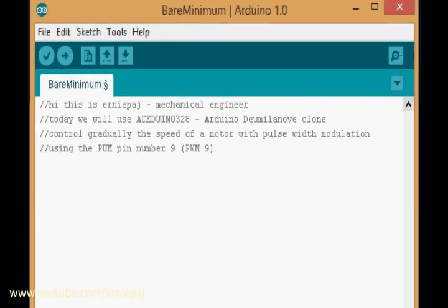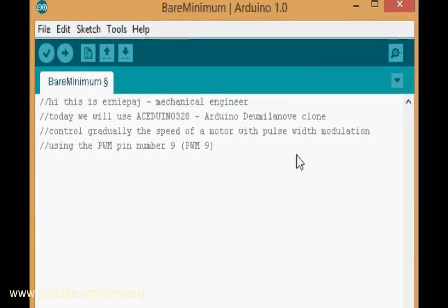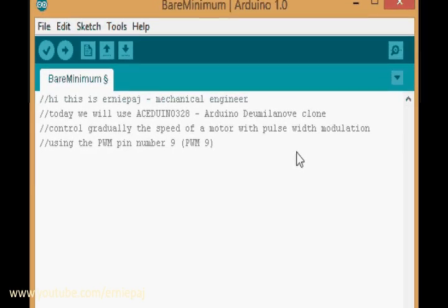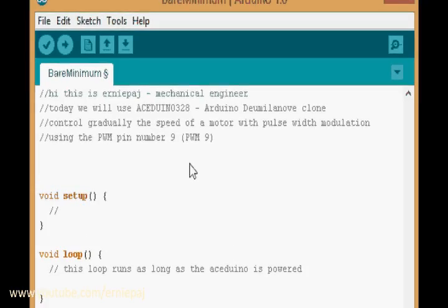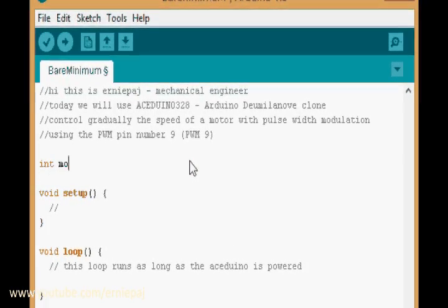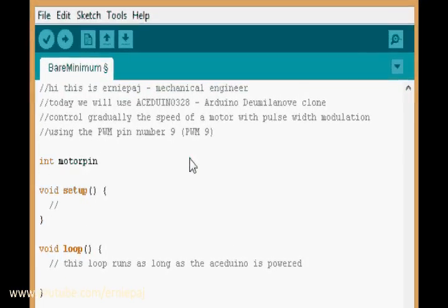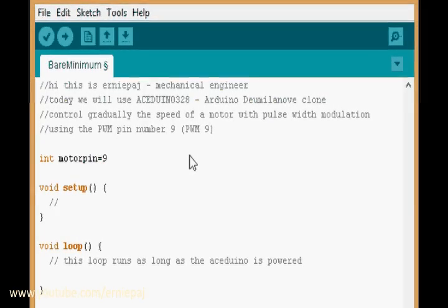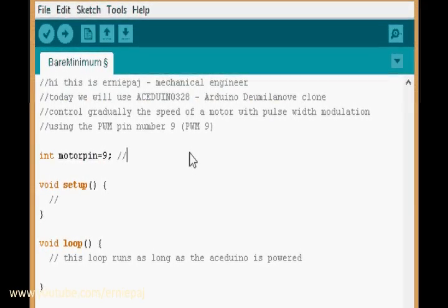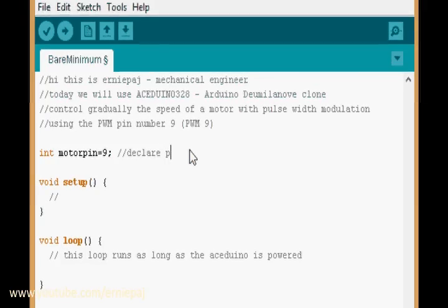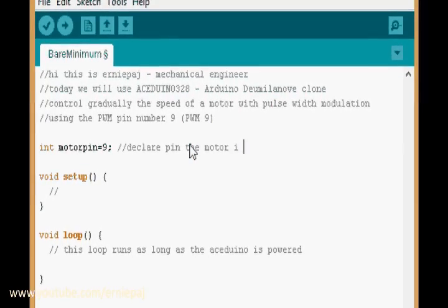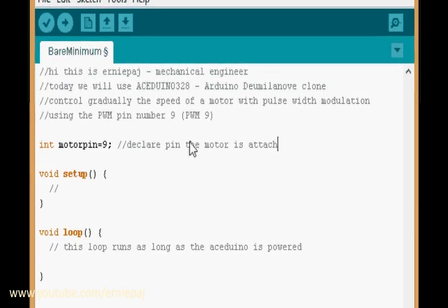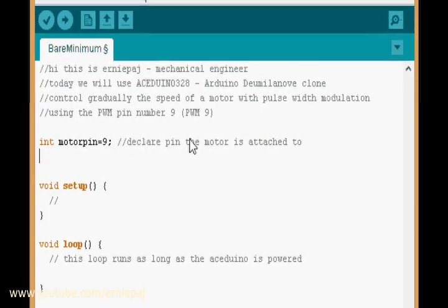Before we proceed with this, it is important that you go have a look at the Arduino CC website and understand how basic syntax works within the Arduino Sketch IDE. So what we're going to do now is set up 3 variables within Arduino Sketch as follows. First, the variable that declares the pin that sends the signal out to deliver 5-volt DC, in this case, pin 9. That variable is called motorPin.